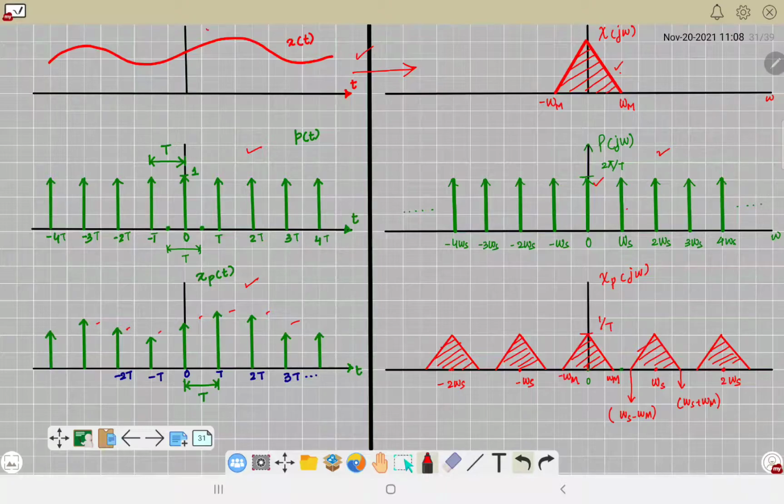But in the frequency domain, it turns out from the mathematical analysis we have done that the result of this multiplication in the time domain is actually equivalent to convolution in the frequency domain, which means graphically, wherever this impulse appears, around that impulse the original signal is built. As you can see, this is convolved with this every time; at every frequency instant where you have an impulse, around it the input waveform gets replicated.